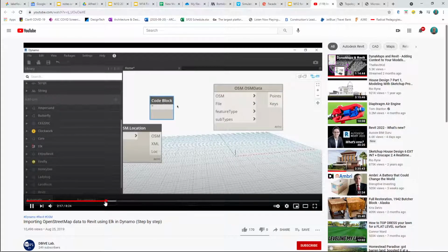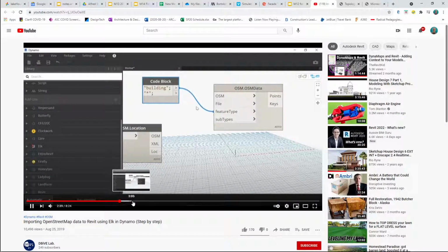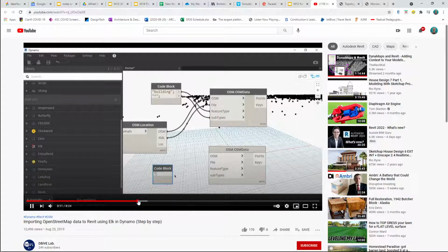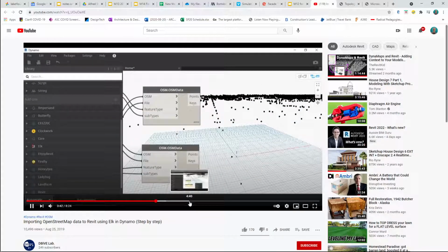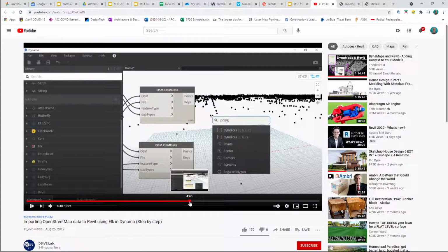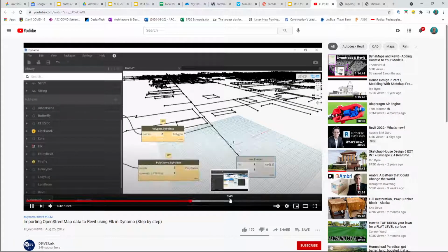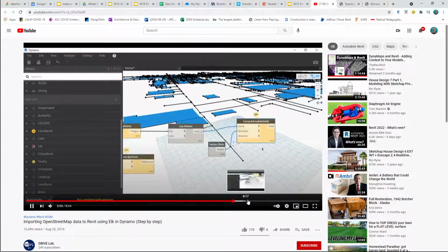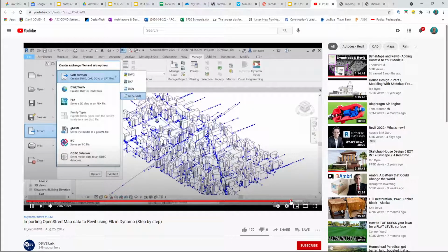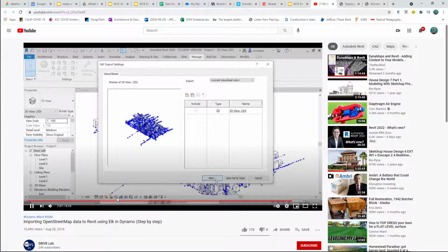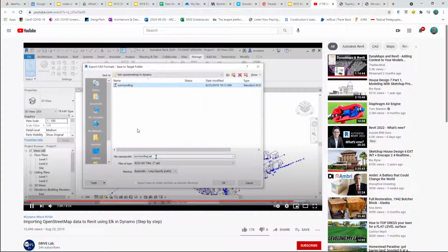And you have to use the software that we are yet to learn, that is Dynamo, to be able to bring in this building information and populate maps. So here we're going through the idea, that's the geometry of buildings being imported, changing them into three-dimensional information and eventual building sets like this, and happening right inside of Revit. So then we have our site context for a project we might be working on.